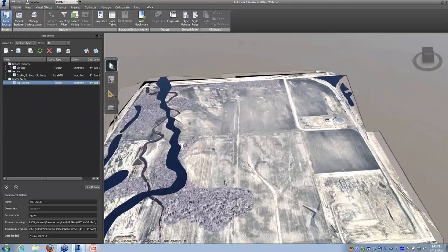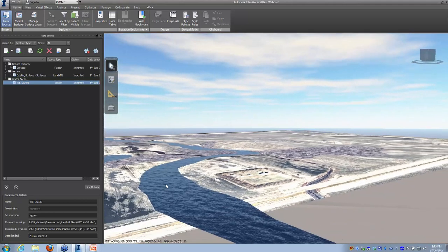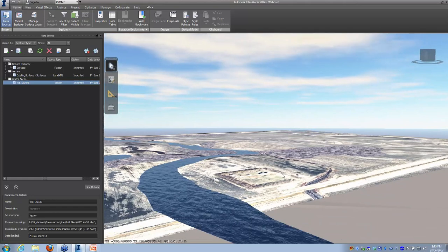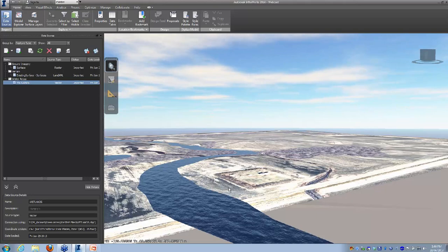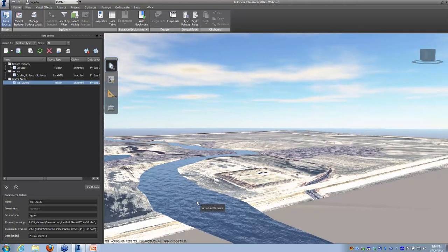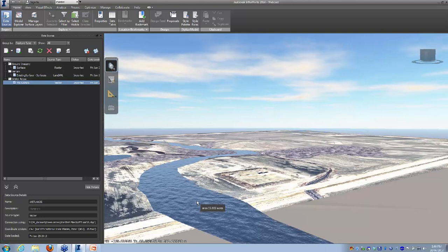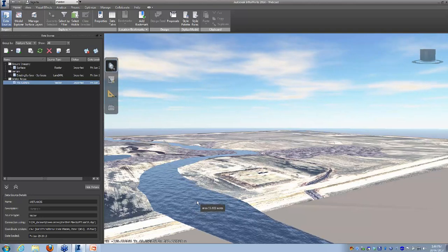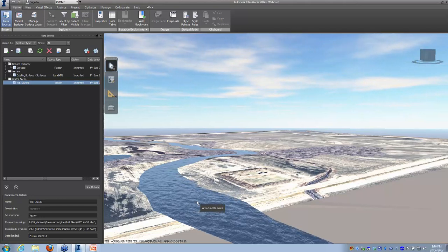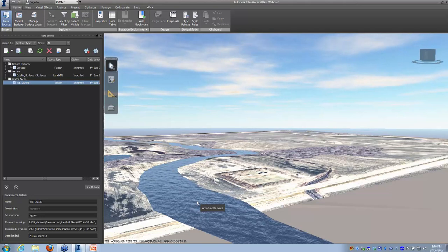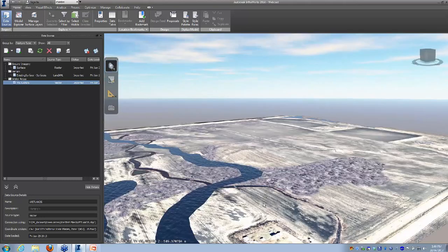Okay, so now we're getting our water areas coming in from the shapefile, and they're being configured up to look like water, which is, they've made the water kind of dynamic and nice in this version. Also, if you hover over that, we should get our tooltip that we asked for. So it's got the text area and acres, and it's got the number from the shapefile, which is the property, one of the attributes of the shapefile, one of the bits of object data. So that's good. That's a good start.